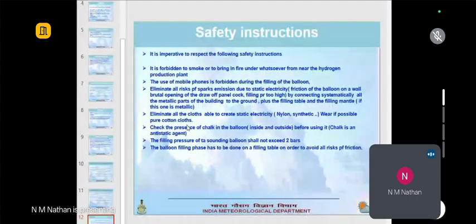In case you are unable to remove that cylinder cap, you should not use anything metallic. You have to use mallet type of things only, to gently tap, etc. If you use a metallic hammer, then that is dangerous.